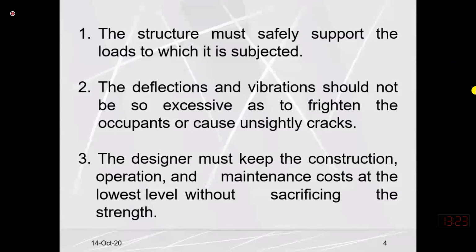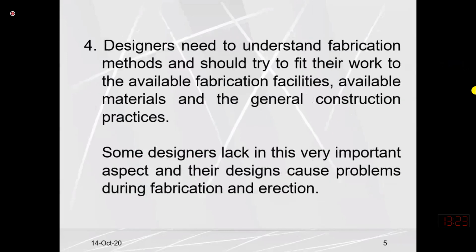Operational costs mean that if I have the option of constructing a bridge by plate girder, then I will not go for trusses, because in trusses the maintenance cost is more. It is difficult to paint all the corners because there are a lot of joints, a lot of members meeting at one point. So I need to select a structure in such a way that it is easy to maintain.